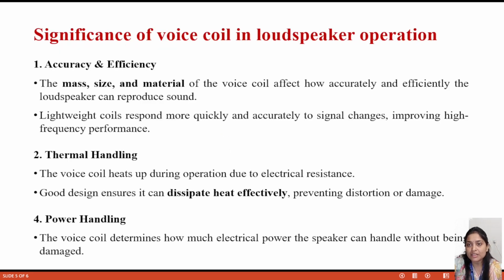Now, what is the significance of the voice coil in loudspeaker operation? One very important point is accuracy and efficiency. The mass, size and material of the voice coil affect how accurately and efficiently the loudspeaker produces sound. Lightweight coils respond more quickly and accurately to signal changes, improving high frequency response. Depending on the application, we will choose the material and the size of the voice coil.